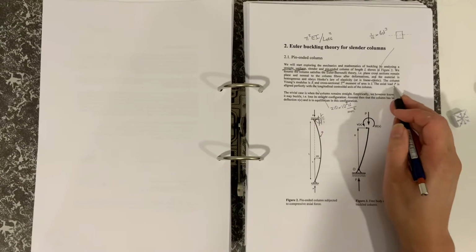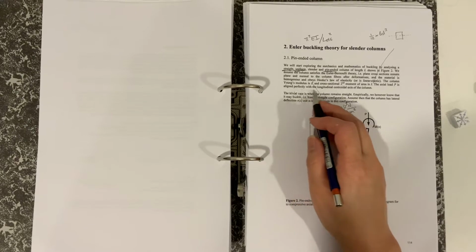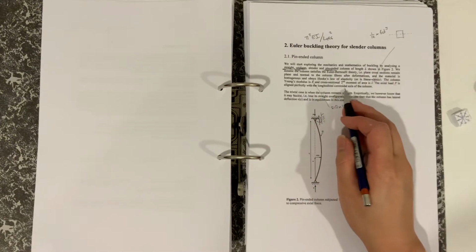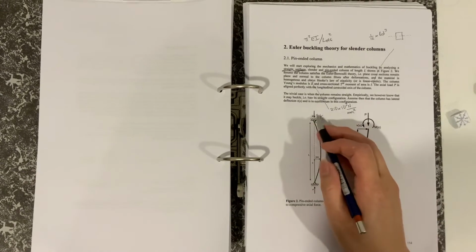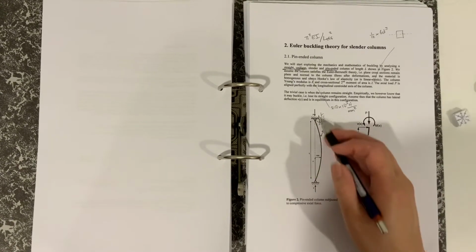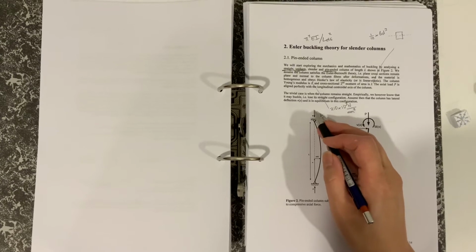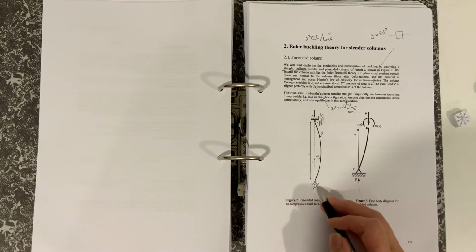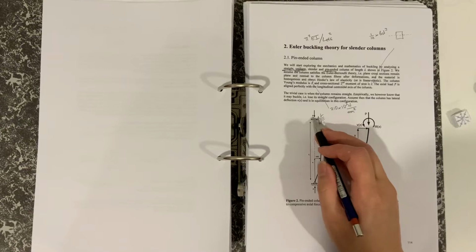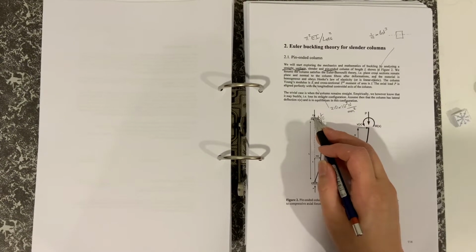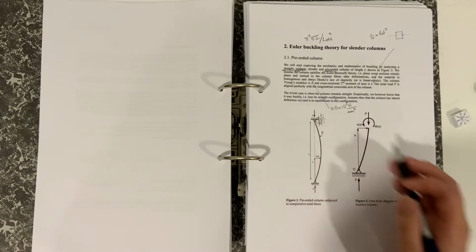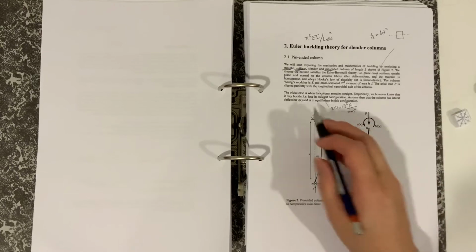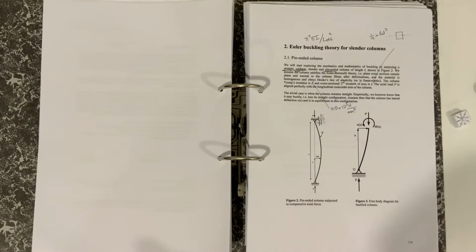Now we're saying the axial force is aligned perfectly with the longitudinal centroid of the column. So that's not something that can be done in the real world, but in this artificial world, we're assuming that the line of action goes right through that line there. So in the real world, with defects, with the way that people make connections, it could be a couple of millimeters out, and that P could be either to the left or to the right. But for this case here, we're assuming that it's aligned perfectly.